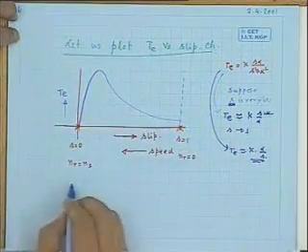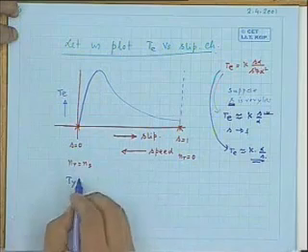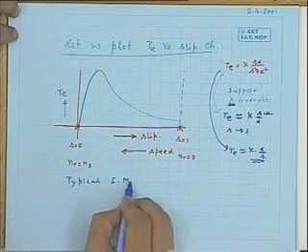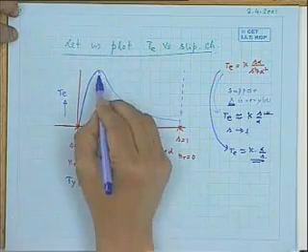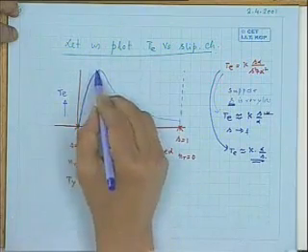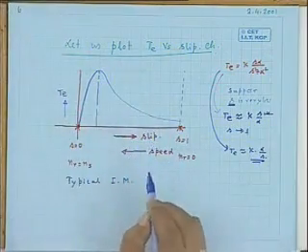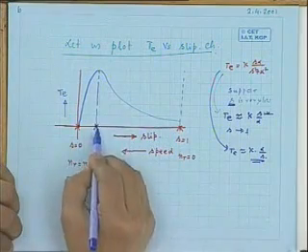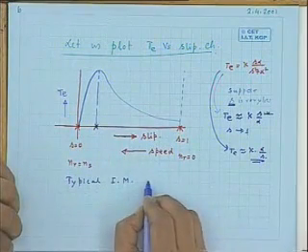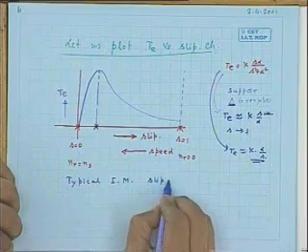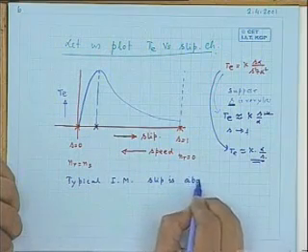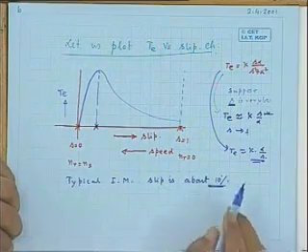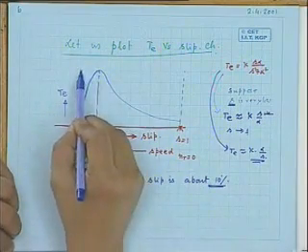Now the question is, in a typical induction motor, this value of slip up to which it remains more or less a straight line, the slip at this point is about 10%, a typical value.